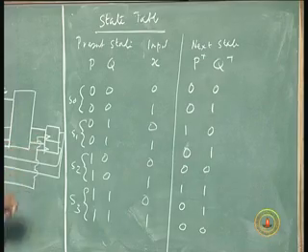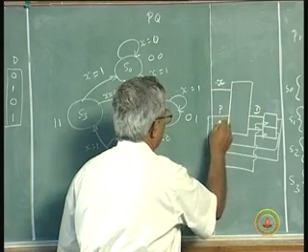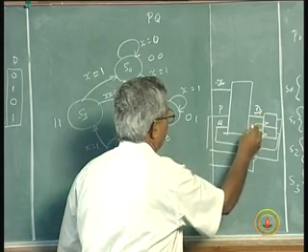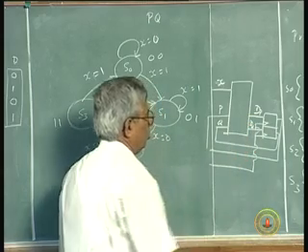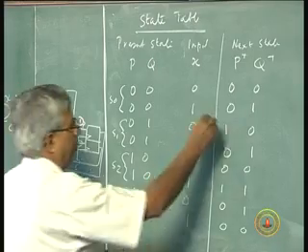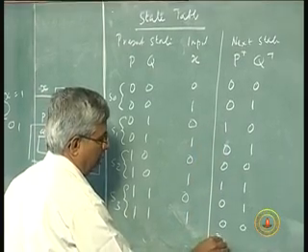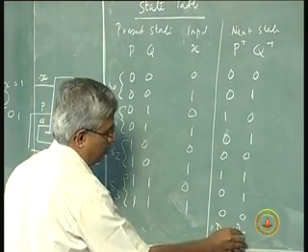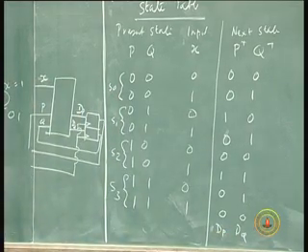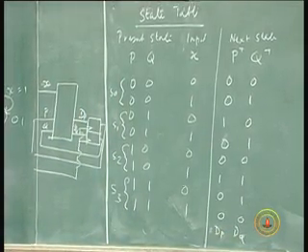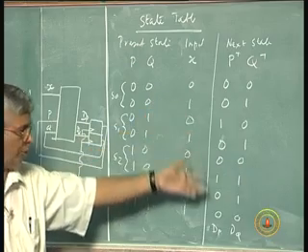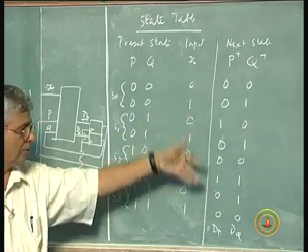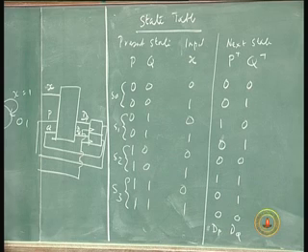in this model. This is a D, this is PQ, no? I called it PQ. So, I call this DP for the D of P flip flop, D of Q flip flop, DQ. So, this is the same as the DP map, it is also the same as DQ. So, what will be the logic required? You have to draw Karnaugh maps using these 3 inputs p, q and x for p plus, which is the same as dp, q plus the same as dq, and then get the steering logic. So that circuit will be completed. We will do that here.